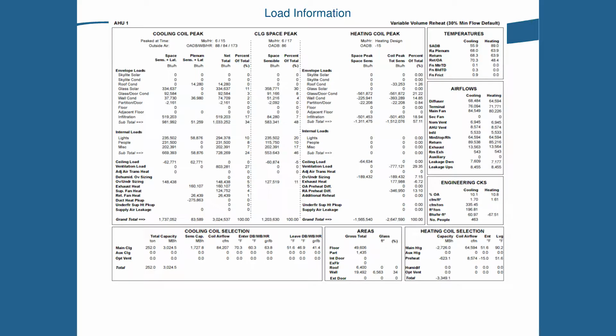Yep. Thank you. Yeah, so those are just the rule of thumb things that people look at: percent outdoor air, CFM per square foot, CFM per ton, that kind of stuff. So you can look at that real quick and make sure you're in the right neighborhood.